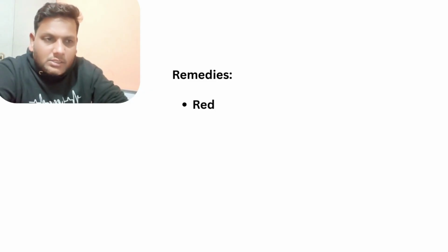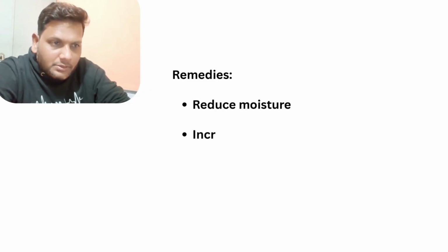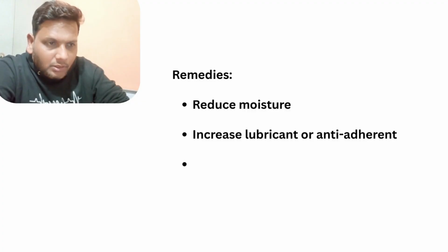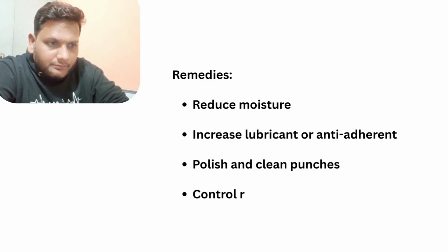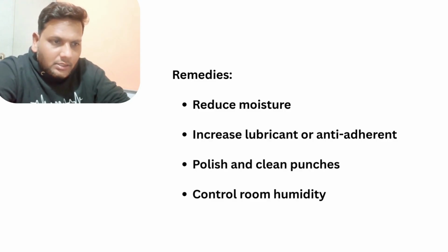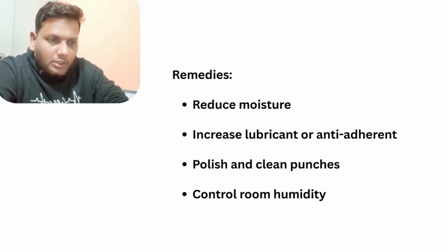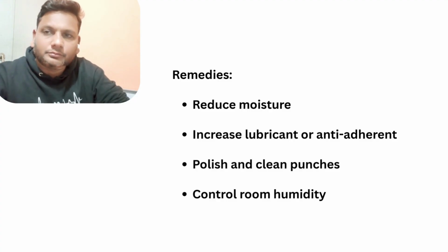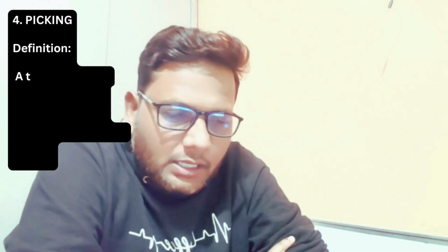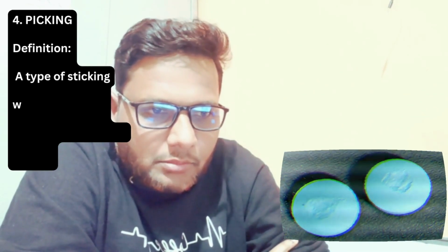Now what are the solutions or remedies for these problems? We can overcome this problem by reducing the moisture content, increasing the lubricant, polishing or cleaning the punches, and controlling the room humidity. And the very next problem which is taken under consideration is the picking problem.